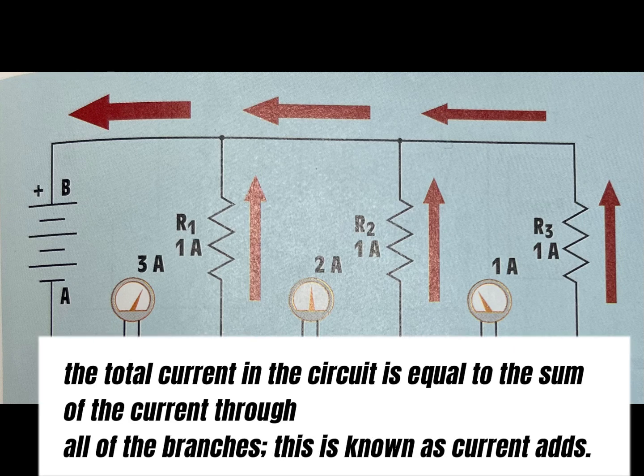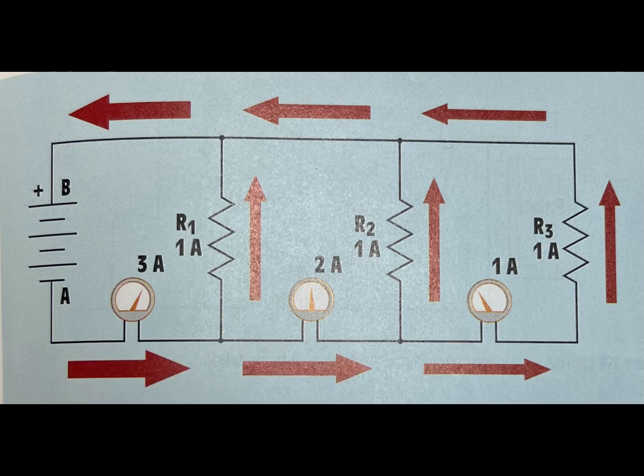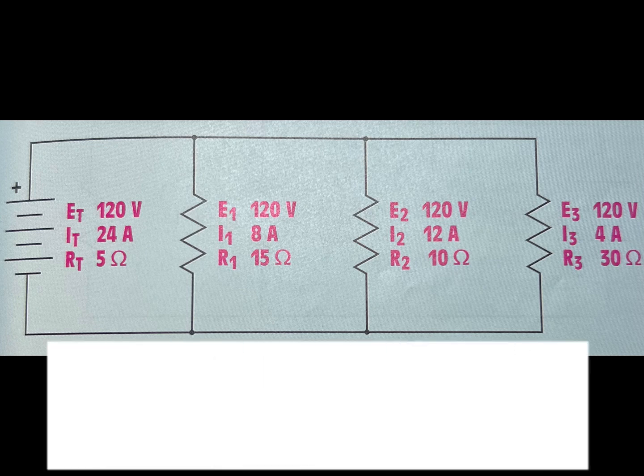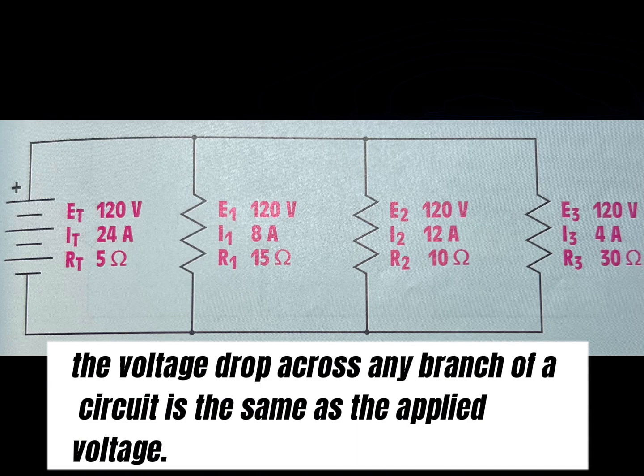In laboratory exercises, students often see the circuit current increase each time a resistive element is connected to the circuit, and they conclude that an increase of resistance must, therefore, cause an increase of current. That conclusion is, of course, completely contrary to Ohm's law, which states that an increase of resistance must cause a proportional decrease of current. The false concept can be overcome once the students understand that if the resistive elements are being connected in parallel, the circuit resistance is actually being decreased and not increased.